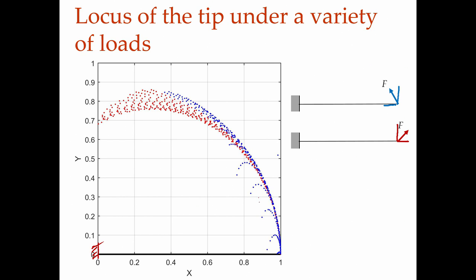If I neglect this, which is kind of like a buckling, when I have a beam like this with a transverse force and now we apply a compressive axial load, this actually tends to turn back a little bit, right. So, this beam would turn something like that, and those points come a little inwards, that is where you see these little blue arcs, okay.